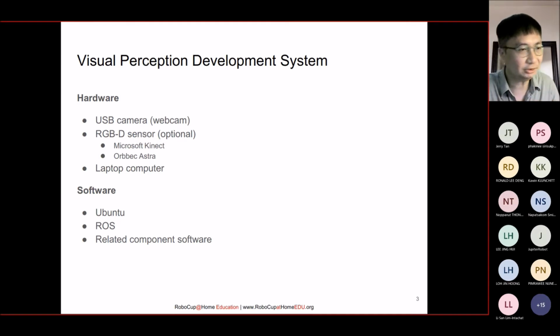Over here in today's class, we will use the Astra, which is the typical RGBD sensor for TurtleBot 2, and also the previous sensor, the Microsoft Kinect, but currently I think it's already out of the market. You cannot find it anywhere, but they work on the same principle. Whatever I show you also works with other RGBD sensors. For example, the Asus Xtion Pro Live is also an RGBD sensor, and it works almost similarly. It's just that the driver you use to run the sensor is a bit different, so you need to get the correct driver. But how it works is supposed to be the same. The examples should be compatible with different kinds of RGBD sensor.